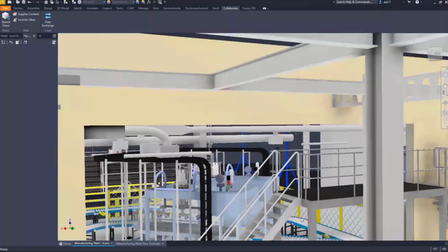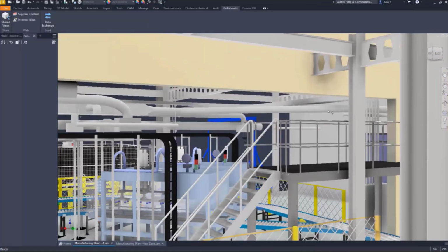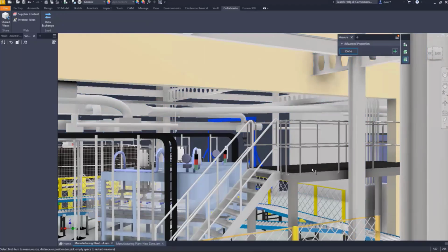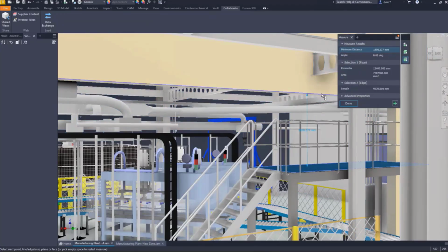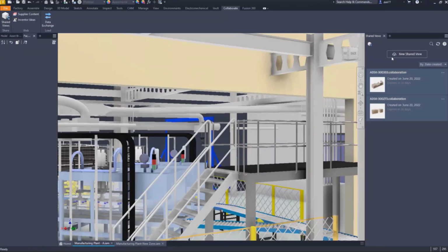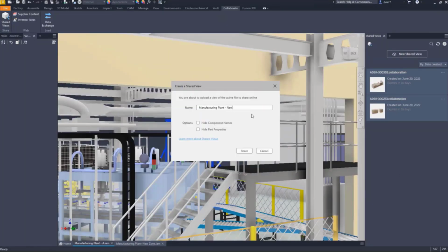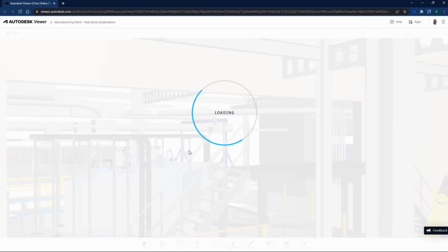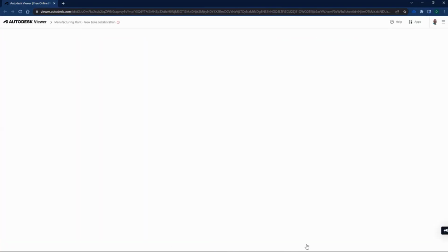In position, but from the visual, I think you can see something is wrong somewhere. You can see the steel structure over there is actually hitting the wall, the opening. So what we can do is ask the owner to give us the data or make some changes to the opening, maybe increase the opening a little bit.